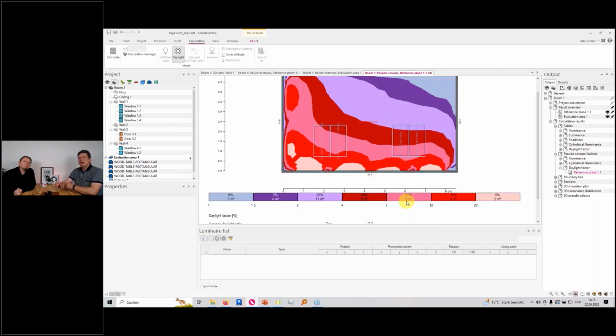And then we will have inside our case gray color the factors. So for example, in this example, for the daylight factor between 12 and 20% is on 30% of the surface, which means this is approximately 6 square meters of the total surface we have inside our room. So it shows the fraction of the room size, split down to the areas of the daylight factors.